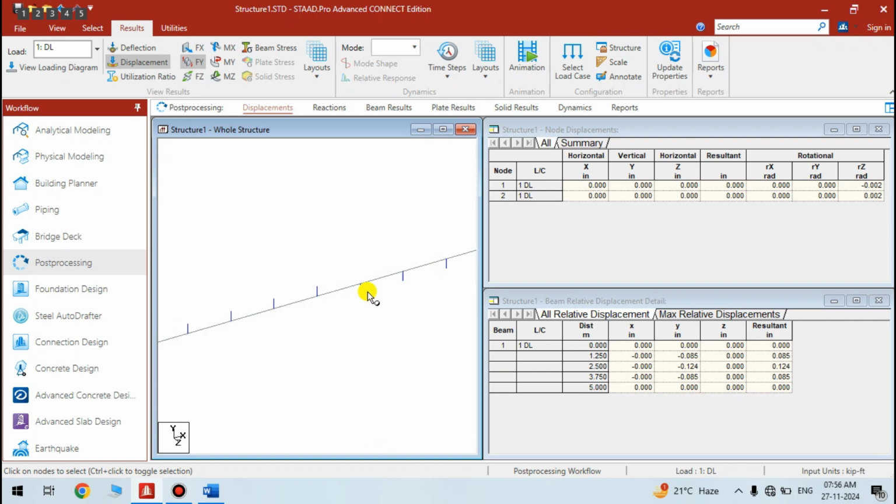Okay, that's why from this section to this section STAAD draws this line directly, but it is actually wrong. The diagram will be like that. The straight line will come up to the midpoint, and then from the midpoint it will go down, and from that point it will go in that side, toward the right side. So don't worry about this portion. Okay.